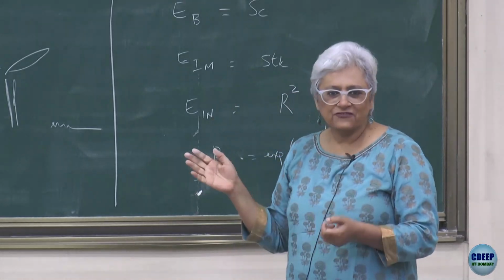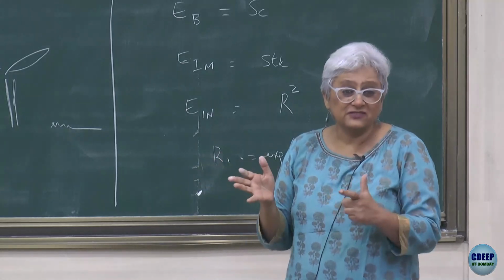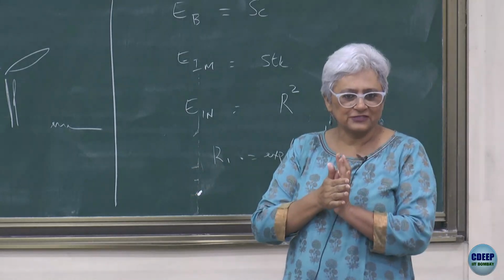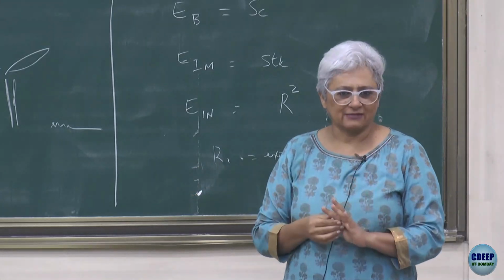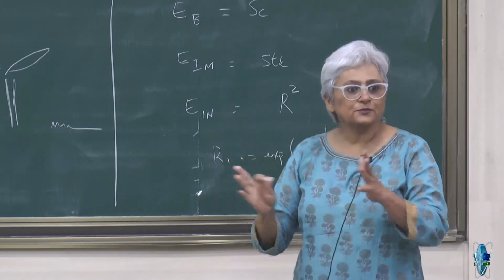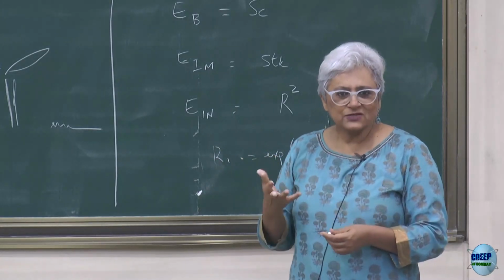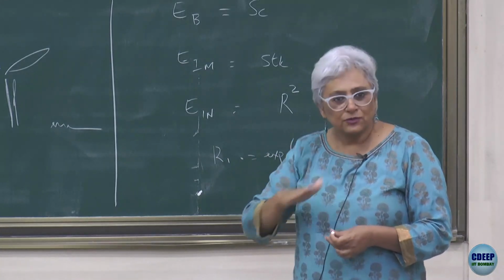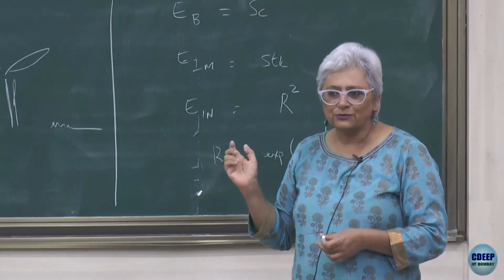It says if I don't have a very inertial particle, it's going to somehow approach the surface and it's going to stick. And that's why that R1 then approaches 1. But as you start having Stokes numbers of any magnitude, you're going to have a chance for it to bounce.